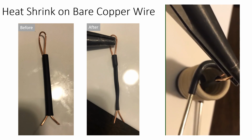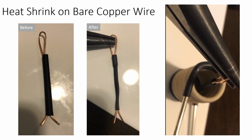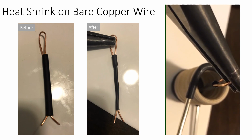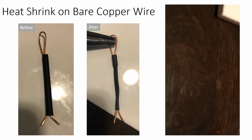When this object was inserted, it took longer to heat than the thicker steel nail that was tried before, but the copper wire did heat up enough to activate the heat shrink. This demonstrated both the effect of using magnetic versus non-magnetic materials and also a method that could be used to heat up a plastic material with an induction coil.